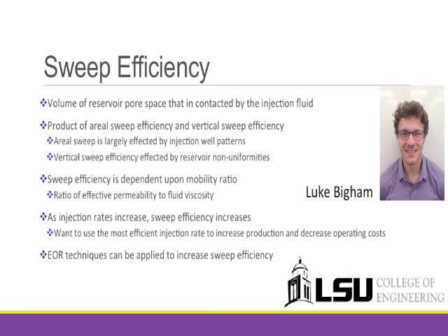Hi, my name is Luke Bigham. Since the project charter, I've been assigned the task of studying sweep efficiency and its relation to water flooding. Sweep efficiency is the volume of the reservoir pore space contacted by the injection fluid. Basically, it's the amount of pore space in the reservoir that the injected water travels through. The overall sweep is a product of the areal and vertical sweep efficiencies. Essentially, these are horizontal and vertical components of the overall sweep.